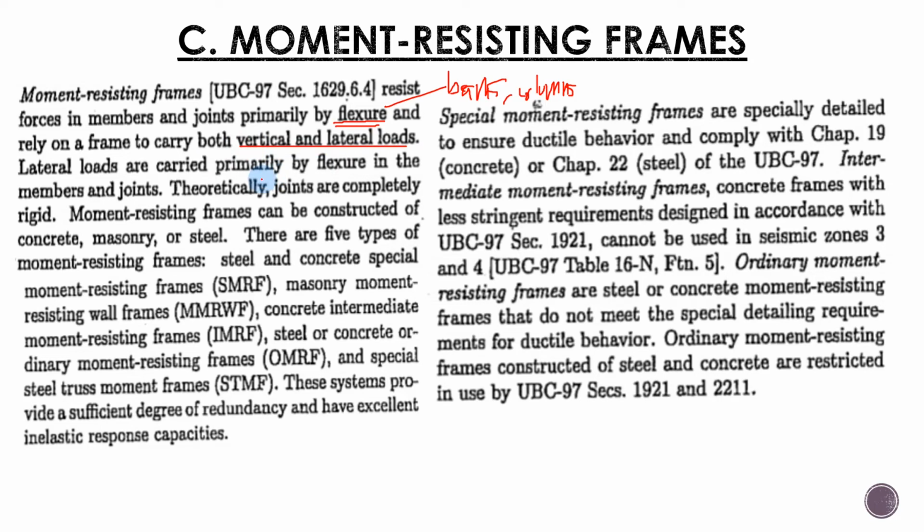So lateral loads are carried primarily by flexure in the members and the joints. Pasabot sa joints is joint between column and beam. So that's why sa moment resisting frame, aside from designing adequate beams and columns, consider po ang joints.